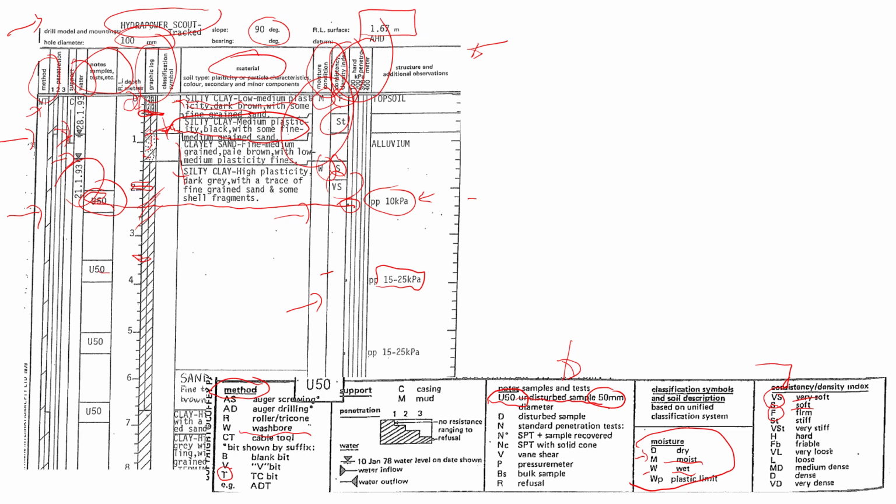Again, this correlates with this sample that was collected, right? So this is the kind of numbers you get. Typically, a geologist or engineer will collect the sample, and then if they have a pocket penetrometer, they just press it against the pocket penetrometer. I have a video about the pocket penetrometer test. Please watch it if you want to learn more about this type of test.